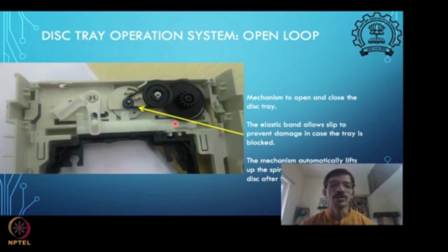For short durations the motor can sustain such heating, and the temperatures don't go so high. But if you keep doing that for a longer duration, the motor coils will slowly heat up so much that the enamel or insulation on the coil burns, and the motor may not function afterwards.